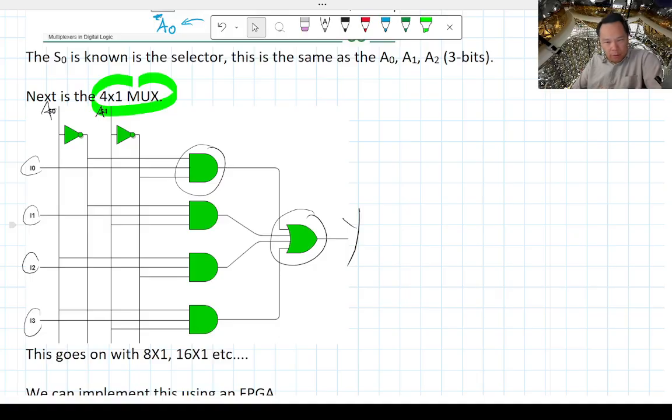And remember, it's pretty simple to make. If you can design an IC that does 3 inputs or 4 inputs, that's fine, but you can also put two input AND gates together to make one 3 input AND gate. And if you need a 4 input OR gate, you need 3 regular OR gates, which you can double up to make the 3 input gates. So these are pretty easy to make.